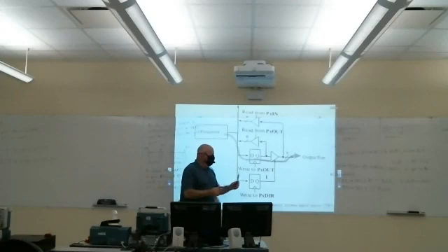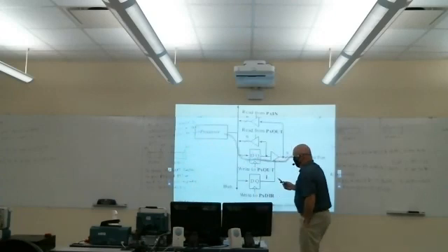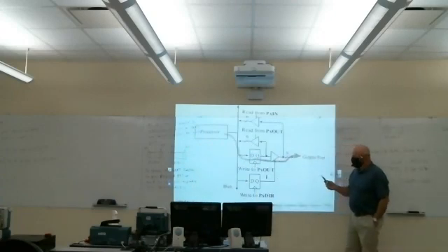And then that would actually set that corresponding pin to a low or high. And on our board, which uses positive logic, if we set it high, we're going to turn those LEDs on, for example.